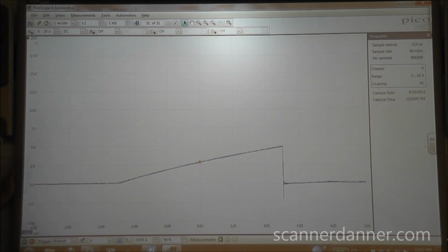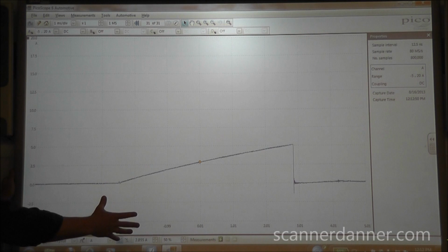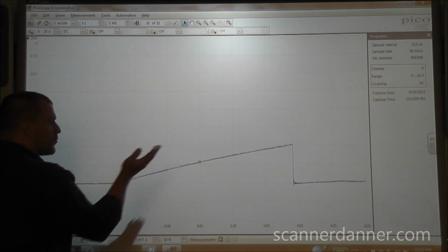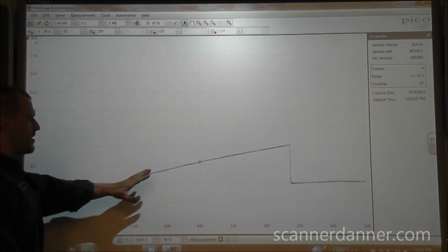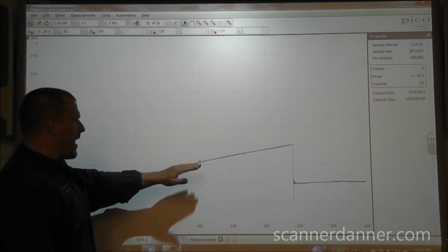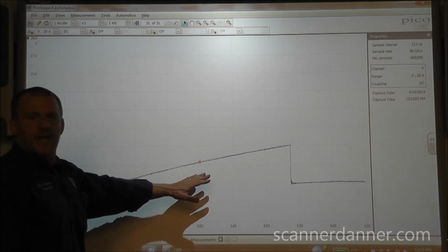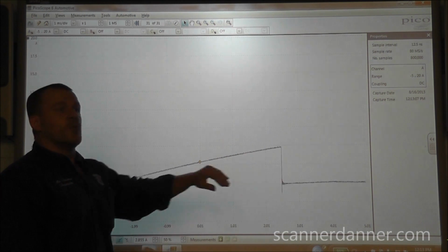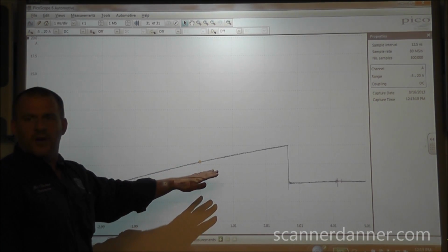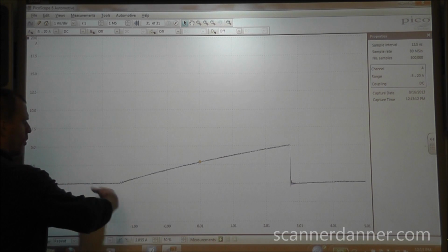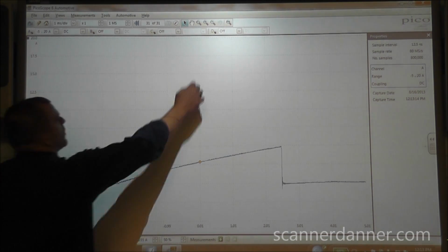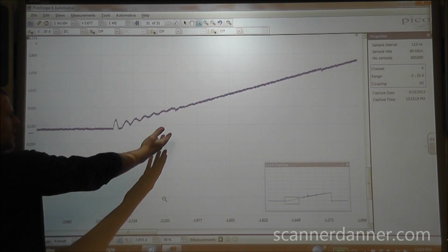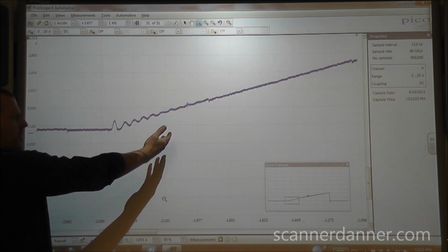And so basically what I've done is I've told the scope to wait and don't draw the waveform until it reaches that point. And so the nice thing about this is the coil firing over and over and over again in the same location. Instead of walking across the screen, we will see every single event right here. That makes it nice if you wanted to look at detail and you wanted that pattern to stay still. So if I wanted to say zoom in on my coil oscillations, I can see them very nicely.